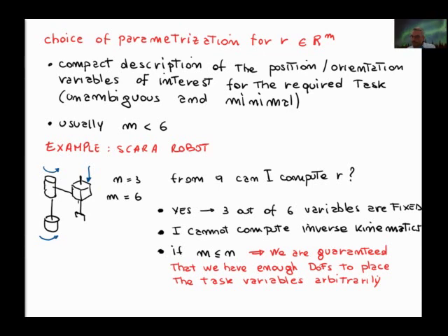Then we also talked about Euler angles, that is a minimal representation because they have 3 parameters. They also have 2 solutions of the inverse problem. So 2 sets of Euler angles correspond to the same orientation, and they also suffer from singularity in the situation, for example, where you have the gimbal lock problem, where you have 2 axes aligned, the yaw and roll axis, for example.